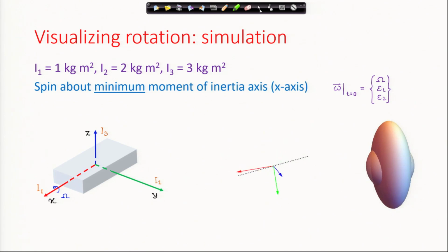You can see the Poinsot construction, the intersection of the angular momentum sphere and the energy ellipsoid is like this, and here the precession is direct precession, the angular velocity is this, and to change values of the lowercase hx, hy, hz, the frame has to reorient, and this is direct precession.